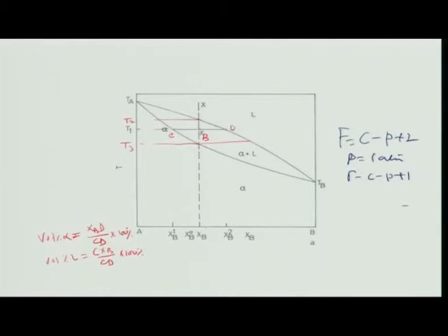You can have any other temperature, suppose a temperature T4 where I know the cutting points, say E and F, and XB is my fulcrum. So you can see here that the volume fraction of solid alpha will be XBF divided by EF.